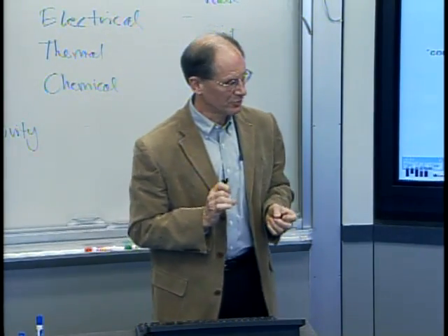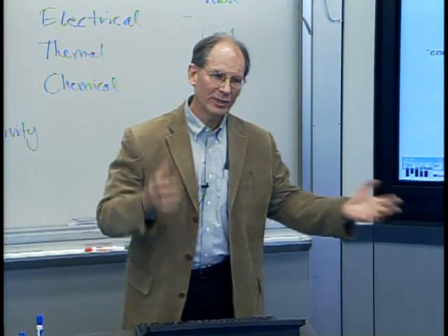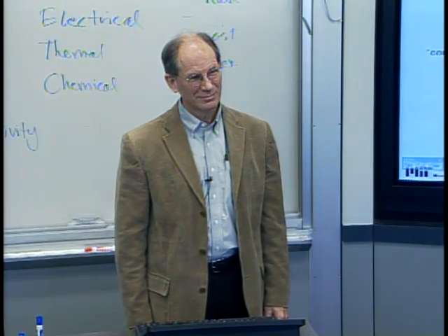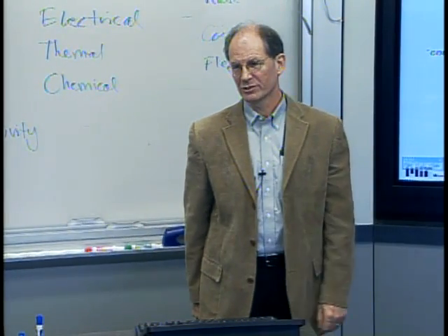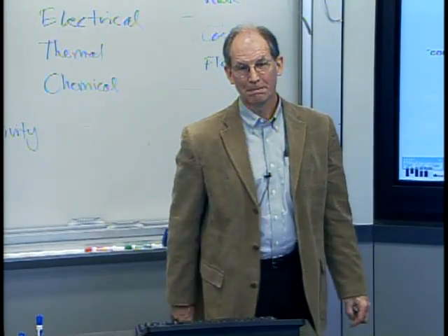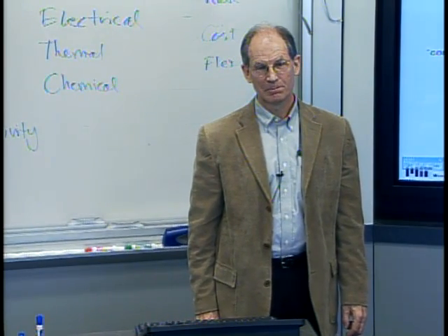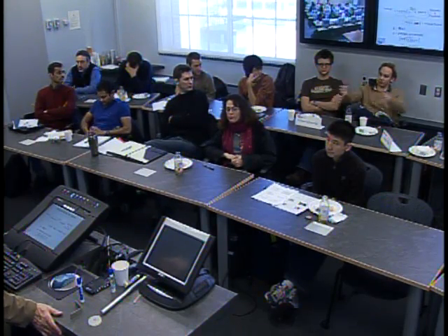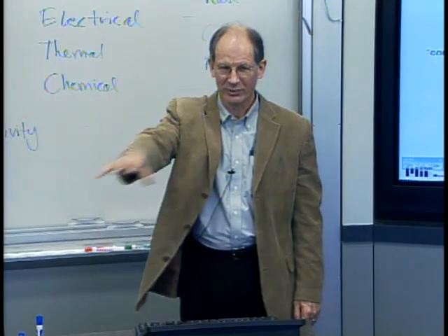And those are useful divisions because, for example, how easily can I change the stiffness of a machine? It can be done. I could buy a new one. I could go in and put in some more supports, or I can take some away and make it less stiff. Kind of hard, yeah. Depends a lot on where I have my process. So if I have a mill, I can take the table out very far and reduce the stiffness. Oh, yeah. Stiffness is not a single quantity. You're right. I can find stiffer regions and less stiff regions.